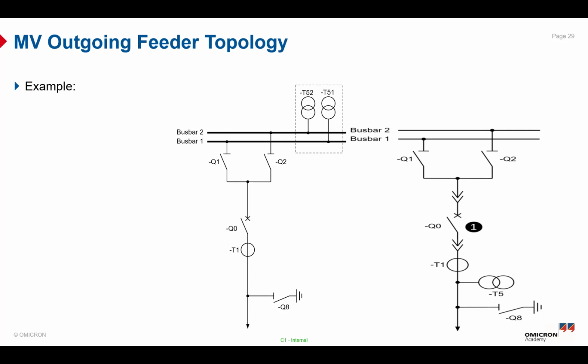So the isolator is designed for use only when no significant current is flowing, not for breaking load current. So it must be operated when the line is dead or de-energized. Also, it can be manually operated to provide a visual confirmation of the disconnection status.